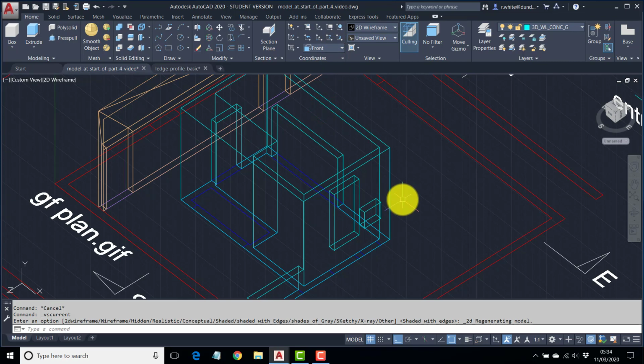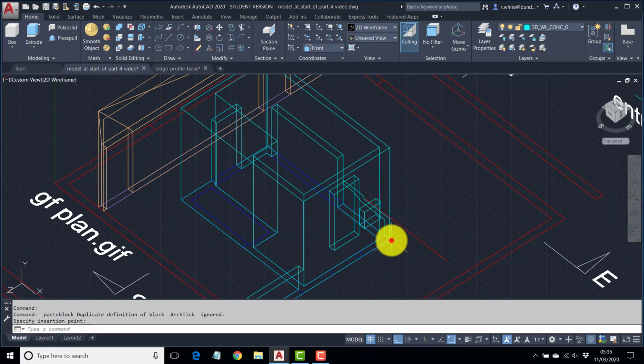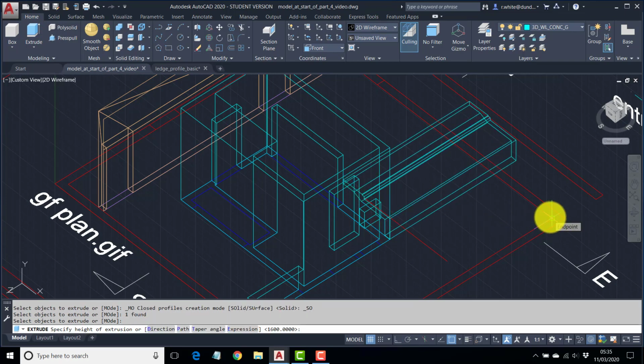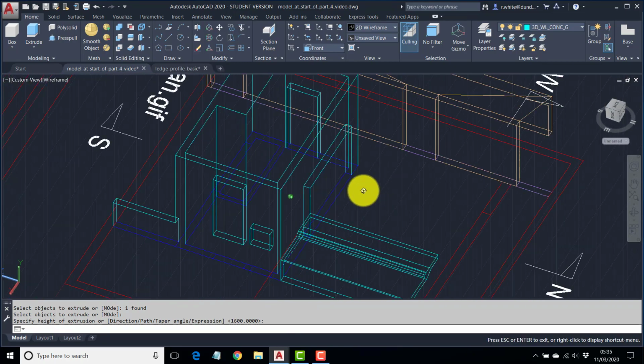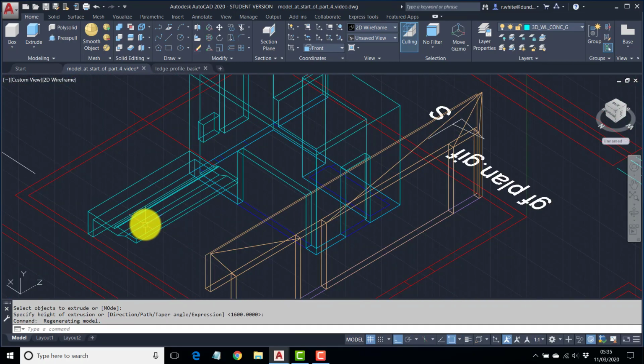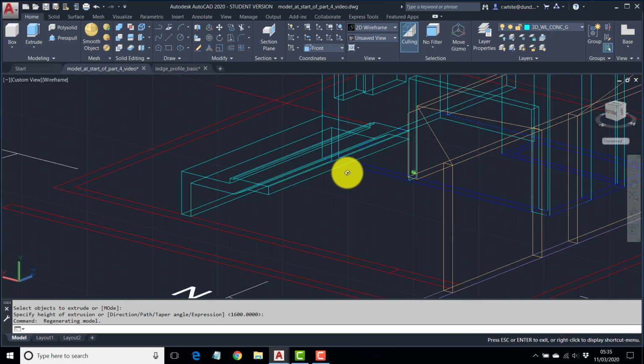Okay, now Shift Control V, the profile's in the right orientation, place it at this point, and then explode it. So X, return, click this, enter. Okay, this can now be extruded to this point. So take the depth from the plan, take it to there. Okay, so all our concrete items done in the same layer.